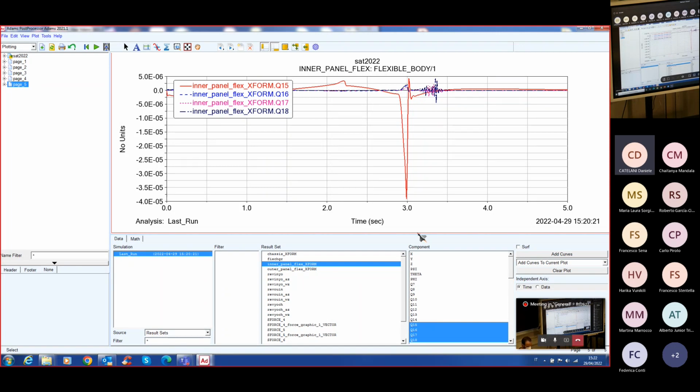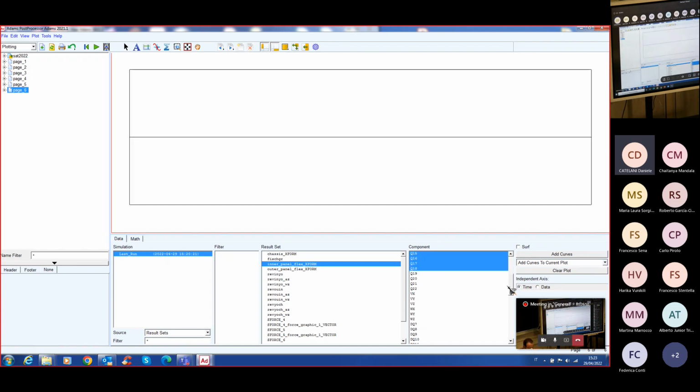So it is impossible, before the analysis, to see which modes are important or not. Every one of them participates in the total deformation of the system. And only by investigating the participation of every mode can we discriminate if some of them are negligible or not.